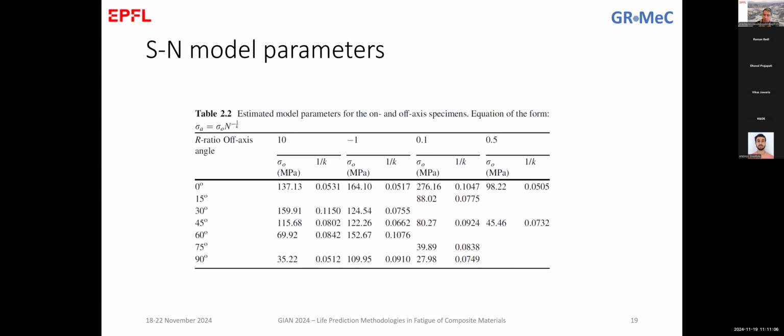And there, depending on the frequency that you are using for your testing, I imagine you're testing at a certain level with a very, very minimum amplitude, very small. So you are at 0.999 in terms of R ratio. And if you assume a certain frequency there, you can do a certain fatigue testing, which corresponds to a creep test.